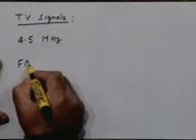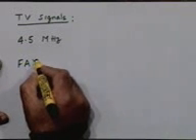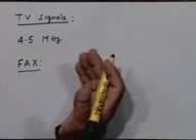I can scan it sufficiently slow, because there's no requirement that by the time I scan it, the picture might have moved somewhere else. The action might have moved to some other action. The picture is still there, the same picture. So I can scan it slow. And that's precisely what you do in a facsimile signal. And that's the reason I can transmit a fax signal through a telephone line, which is designed to carry only 4 kilohertz of bandwidth, because the rate of scanning is under my control.